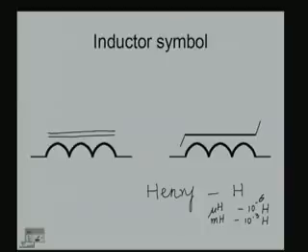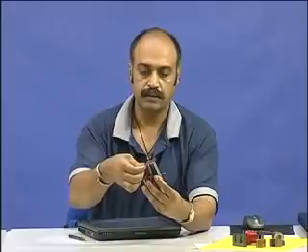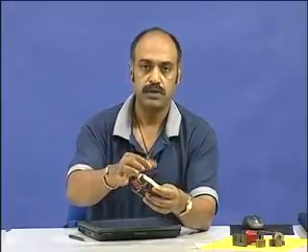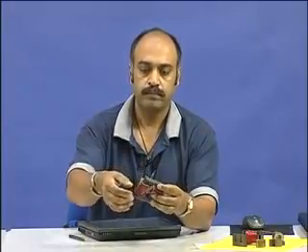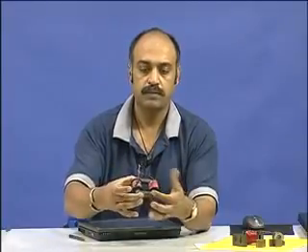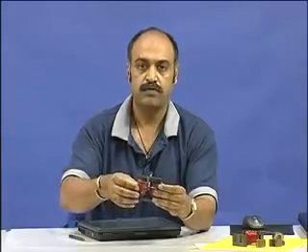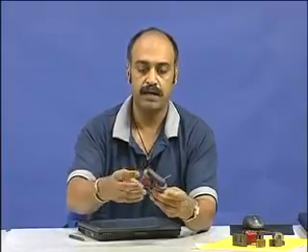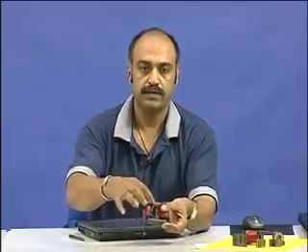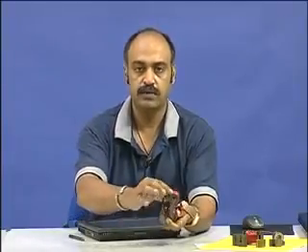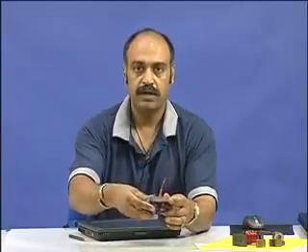Now, let us see some practical real world inductors. You see here, this is a practical real world inductor. You have these two terminals coming out here, and there is a core here and the two coils here. Of course, here for handling the current rating, these two coils are paralleled. You see that these two wires are paralleled here, taken out here, the other two ends parallel and taken out here, but it can also be as well just one coil here.